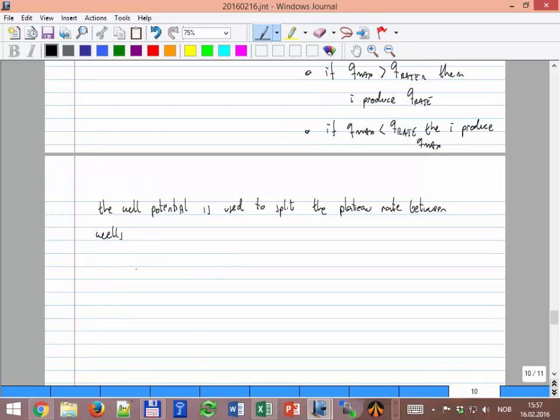So we have the Q potential of the field, which is just equal to the sum of all the potentials for each individual well, from i equal to 1 to n, where n is the number of wells. Then you can calculate a factor for each well, xi, equal to the Q potential of the well divided by Q potential of the field. Right? And if everything is operating at the minimum flowing bottom hole pressure, then I will get this split of rates.